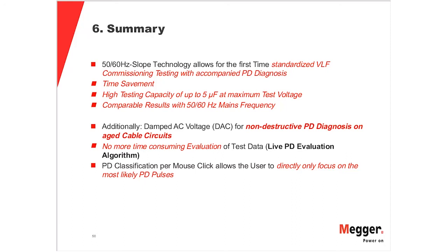You have seen that the ability of testing high capacitive load is very limited with VLF sinusoidal, because it dissipates the energy over a resistor and burns it as heat, while we keep on using the energy with the VLF cosine rectangular, and we are therefore able to test much longer pieces of cable, up to 20 kilometers.